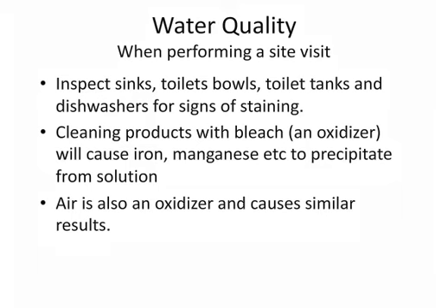I always, by the way, have to go into their bathroom, even if I don't have to go to the bathroom, because I want to see the toilet bowl, and I'm going to lift the tank lid and look inside, because anytime you have some of these toilet cleaning tablets, typically those have some bleach in it. Bleach is an oxidizer, and anytime there are components in suspension in that well water, and you add an oxidizing agent into that fluid, it's going to precipitate out of solution, and it's looking for something to attach to. So typically, you'll see that in the toilet bowls.